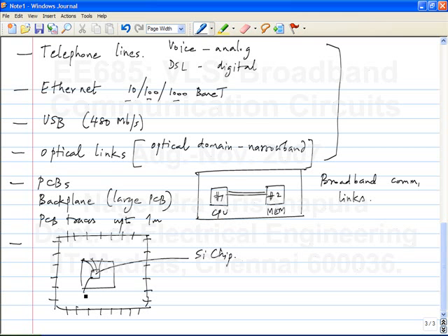So you have small wires about 25 microns thick connecting the chip to the package, and on the chip you have traces just like you have on a PCB connecting the bond wires to the pins. So this is how you make connections between the outside world and what is going on the silicon, right?